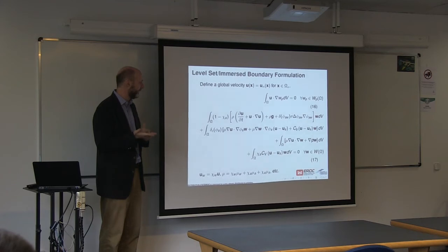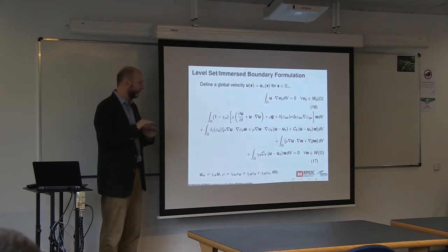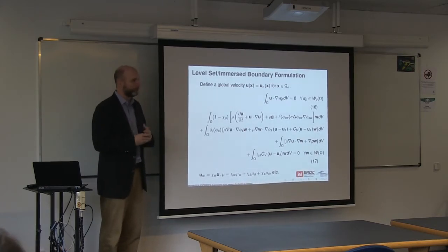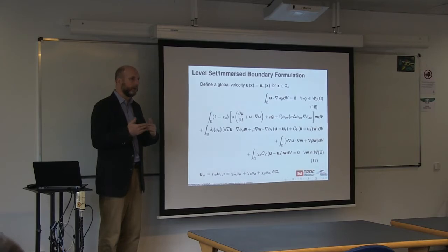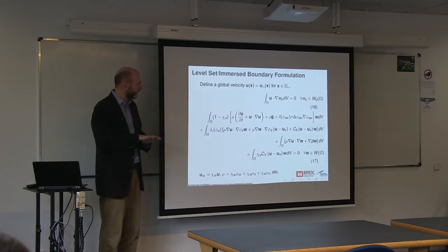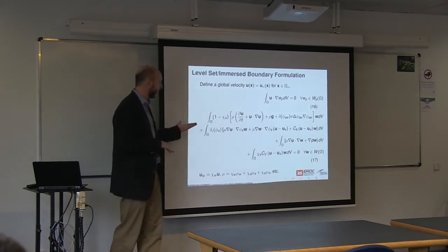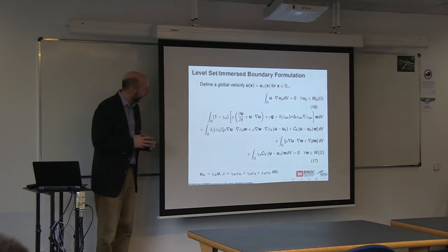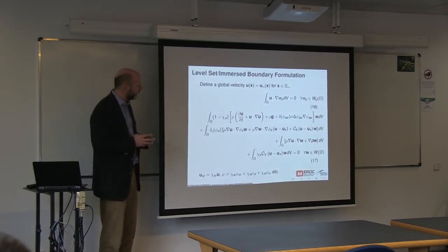And we were trying to avoid that and specifically avoid assumptions about the actual representation of the interface that we were using. So if we wanted to use quadratic level set methods or cubic level set methods, then the cut cell problem there is somewhat more complicated than just intersecting a plane with a cube or a plane with a tetrahedron. And so this way, we were somewhat released from that constraint. We could use higher order methods for the level set representation.